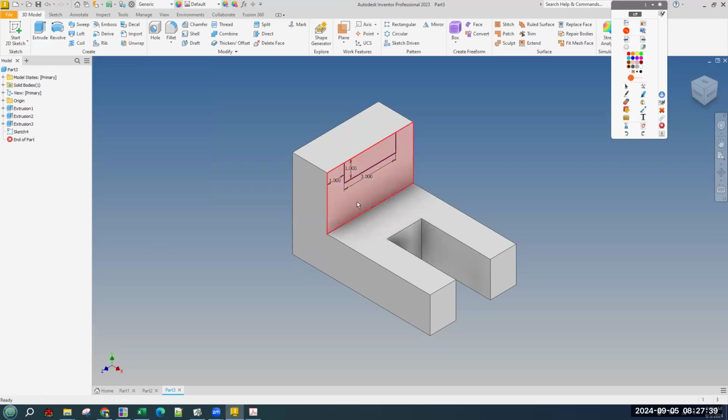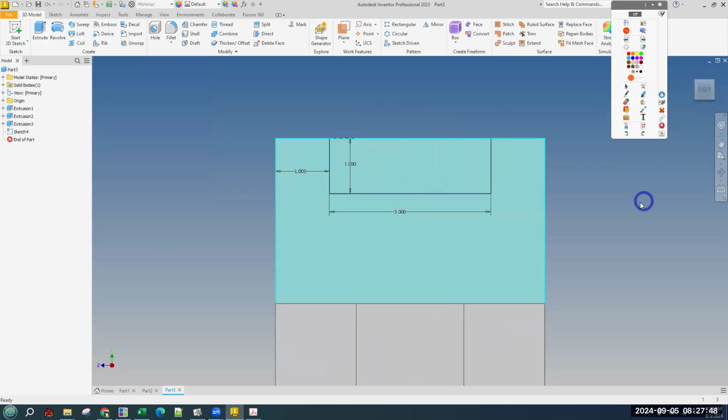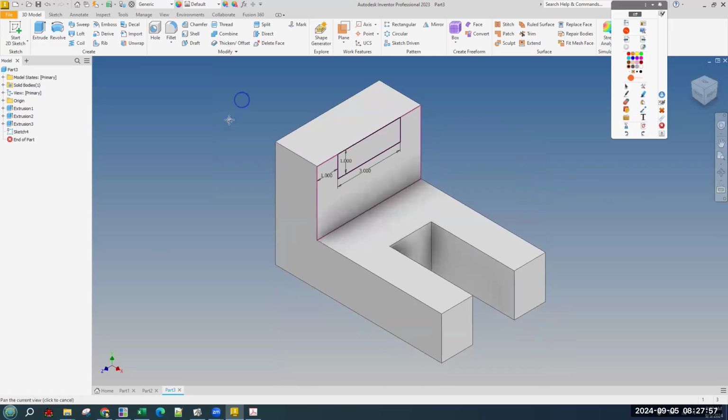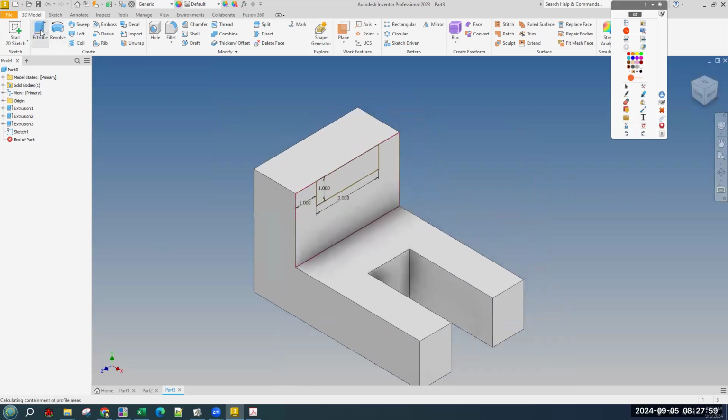Make your sketch on this face. So you need to look at it from like a corner. So yeah, that's that face right there. Yeah. And then the rectangle is 1x3, 1 tall, 3 wide, but then you have to make it 1 from the side. All right, let's wrap this up, and then I'll come around and do more individual help. Let's extrude.